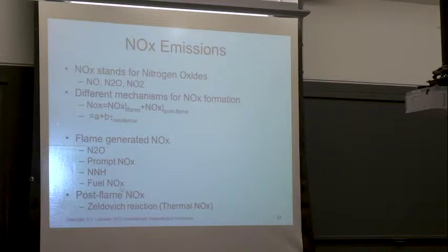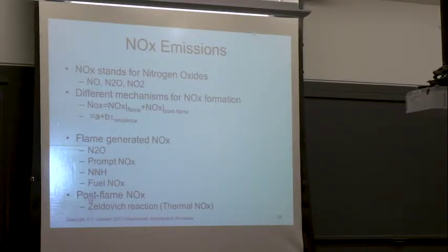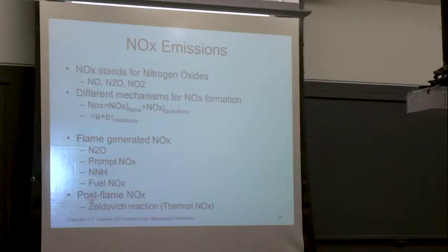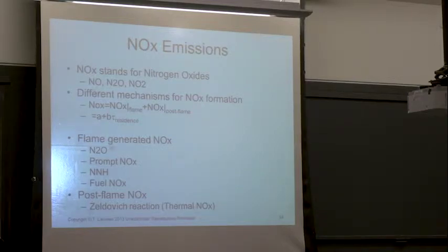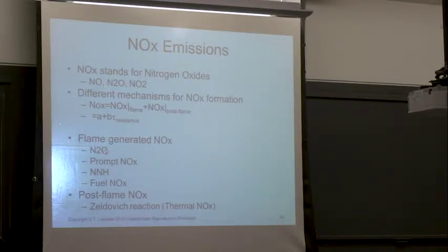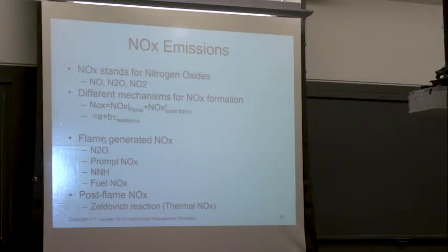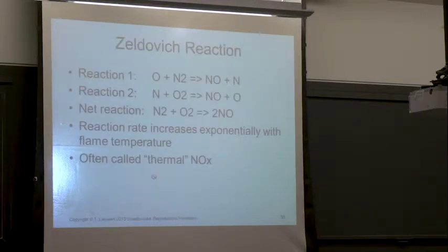Post-flame NOx is generally called thermal NOx or Zeldovich NOx. And again, the idea is once you heat that air up, it's just going to spontaneously react. So if you give it 10 milliseconds, it's going to form a certain amount of NOx. If you give it 20 milliseconds, it's going to form twice as much NOx. So that's the residence time issue. And then you also have flame-generated NOx, and there's a variety of different mechanisms by which NOx can form in the flame. Somebody already pointed out that as you have more higher hydrocarbons in your fuel, you get more flame-generated NOx. Let me just jump over that.